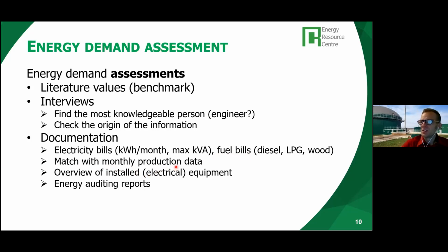If you have this information, try to match it with the monthly production data, so that in the end you may get your information in consumption per ton of product, and it will then also help you making projections for other months that you may lack the information from.